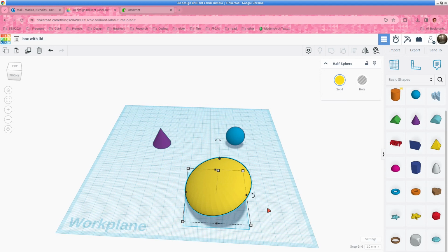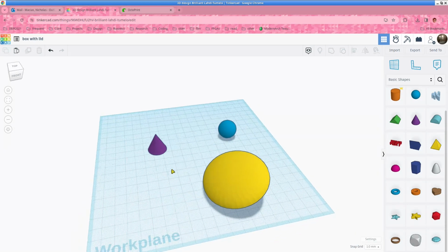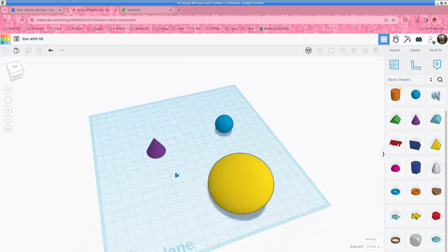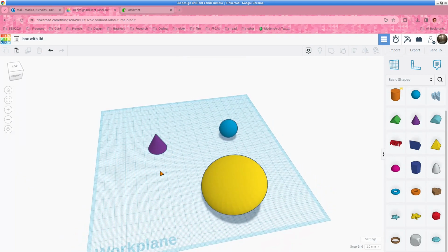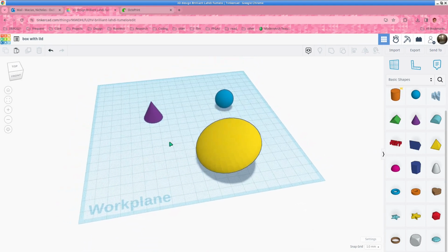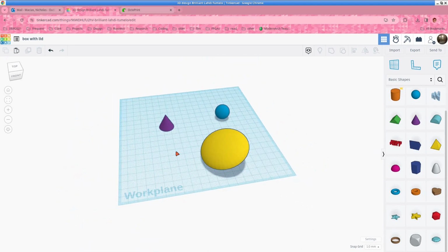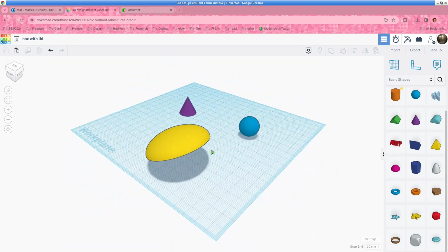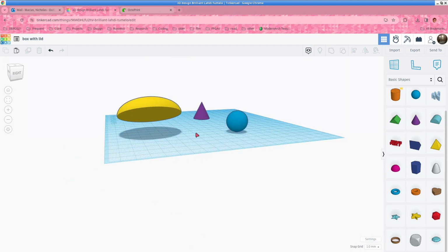But basically, if I click and hold the left mouse button on the surface, that's how I can select objects. So I can draw boxes around objects. If I click and hold the right mouse button, I can move my viewpoint, right? So I can tilt the plane in different directions. If I click and hold the scroll wheel, I can just move the thing in my field of view. If I just use the scroll wheel, I can zoom in and out. And so that combination lets you sort of get to whichever objects you want.